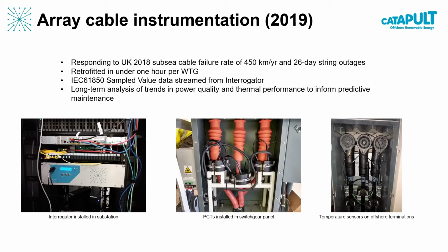The idea we wanted to explain here is that you would only bring out your fiber, connect it to the first, second, and then third phase conductor, or then run along to the terminators and connect some further temperature sensors, then bring it back to the panel, and the fiber continues to the next location.